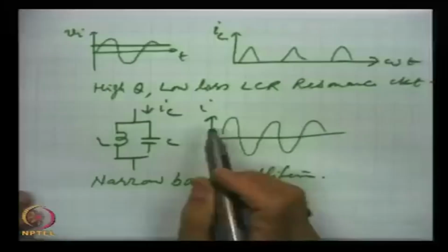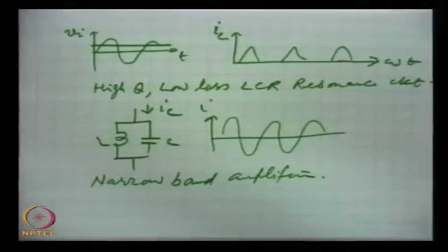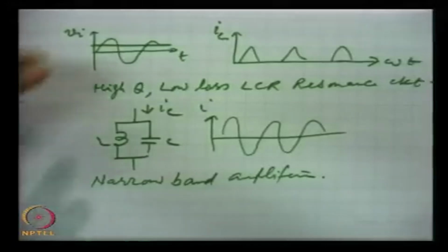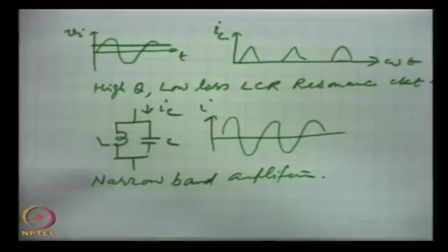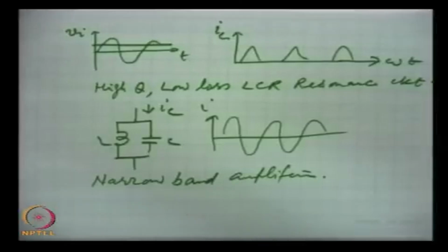High power carrier waves are to be generated, their efficiency will be a big consideration, and in class C amplifiers, the LCR circuit is tuned to the carrier frequency, and from here the high power pulses will be transmitted. So, this is the classification of amplifiers: class A amplifier, class B amplifier, AB, and class C amplifier.